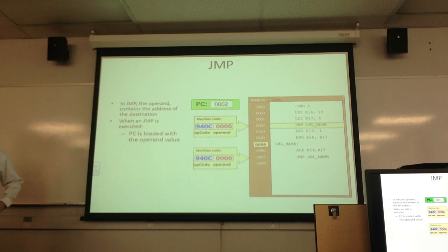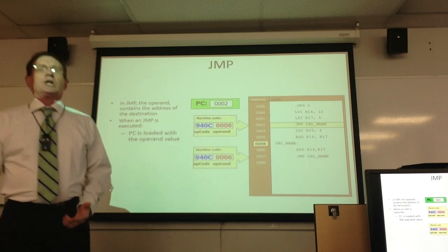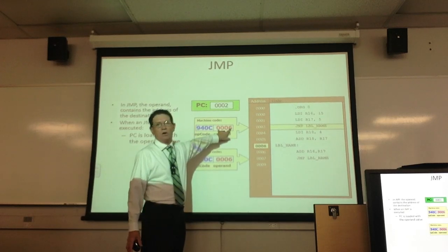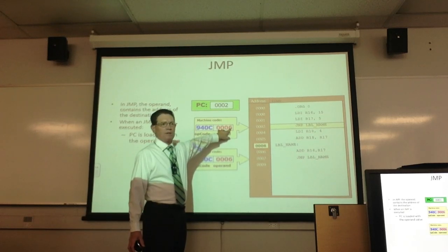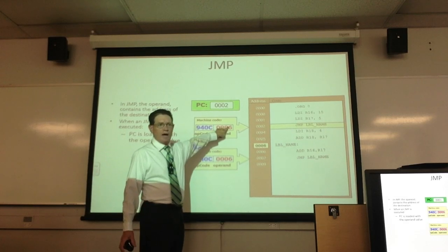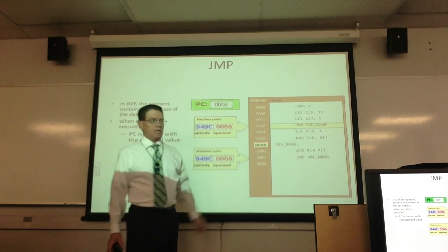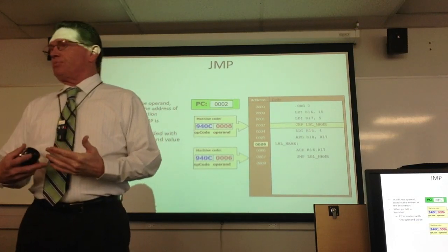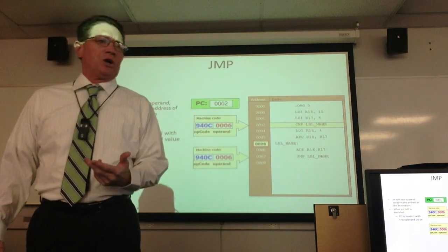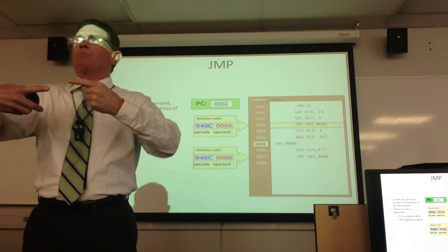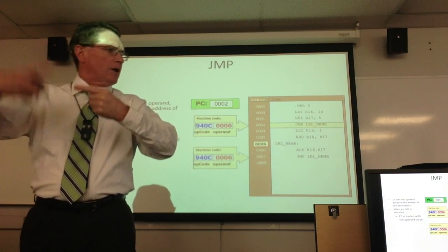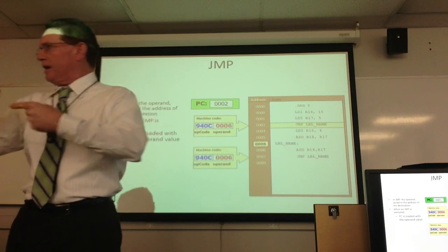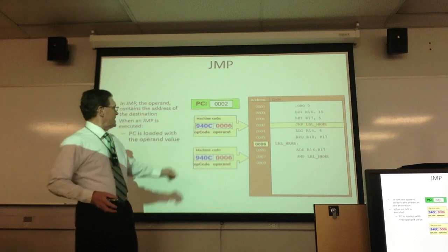That's why we have something called a relative jump. What I'm allowing you to do here is giving 16-bit addressing on the entire flash memory. This is the address of where I'm going to go to. It's 16 bits. If I have a very small, tiny amount of flash memory, you can use what's called a relative jump, which only allows me to jump within, I think, plus or minus 2K. So it allows me to jump around in like 8K of addressing, or 4K of addressing space. So that's the key here.